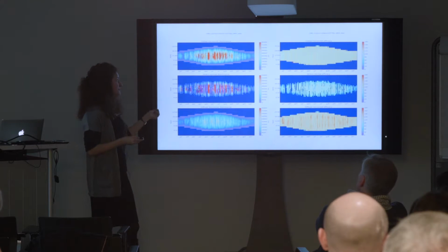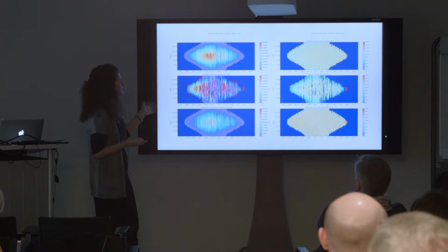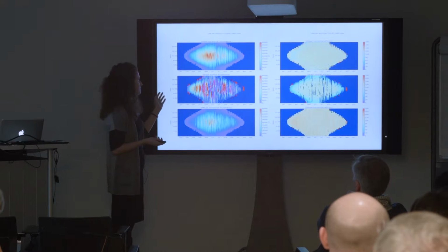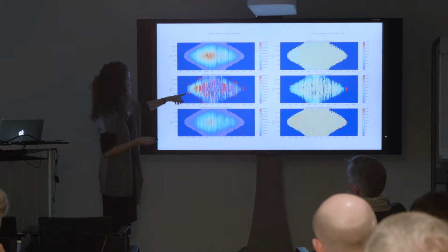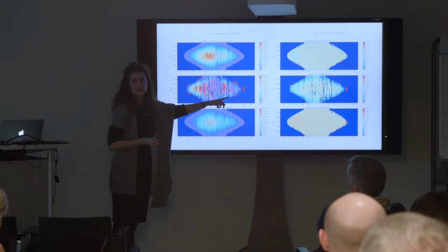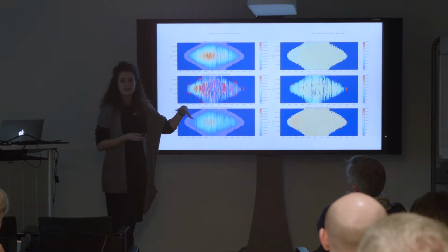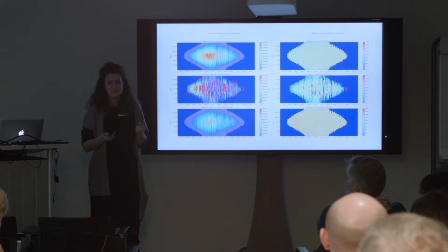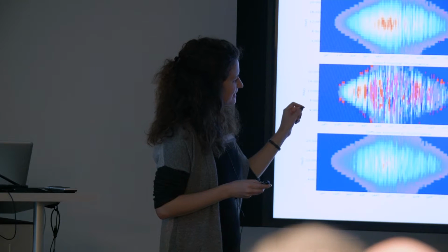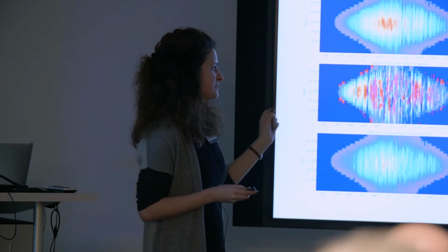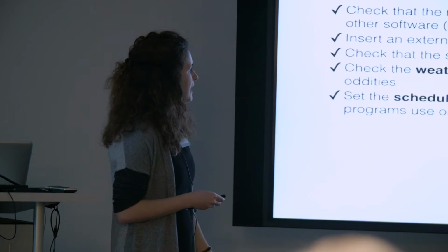This is a climate file for London. It looks very good. But for example, this is a climate file for a place in Canada, very high up north, and it has a lot of infinite values here where the sun angles are low. So at sunset and sunrise, it just blows up. And so you just delete those or be sure that the software handles those.